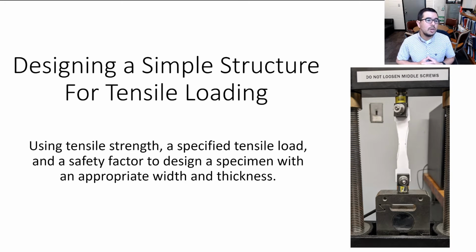In this video, we will discuss how to go about designing a simple structure for tensile loading. We will use tensile strength, a specified tensile load, and a safety factor to design a specimen with an appropriate width and thickness. And this is one step toward the project where we're going to test these specimens during class.